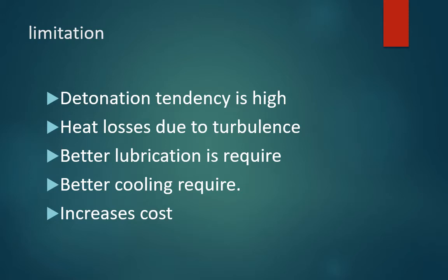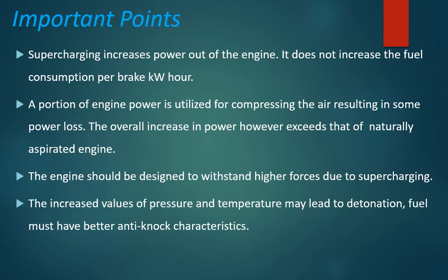So thereby, with all these points, when the detonation is increased, when the turbulence is more, when the lubrication system is to be improved, when the cooling system is to be improved, it could obviously increase the cost and the complexity of the engine. So this is the limitation part of the supercharger. Summarizing the important points: supercharging increases the power output of the engine. It does not increase the fuel consumption per brake kilowatt hour. A portion of the engine power is utilized for compressing the air, resulting in some power loss.